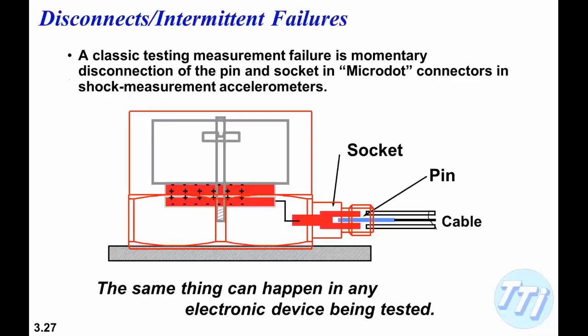Another possibility is intermittent failures, intermittent disconnects, and this is a problem that I have actually run into. What I've got here is an accelerometer with a microdot connector on it, and the problem here is that we got some cables that had an oversized pin in it, and this worked fine until we disassembled this and remounted the accelerometer and hooked it up with another cable that had the pin that was the right size.